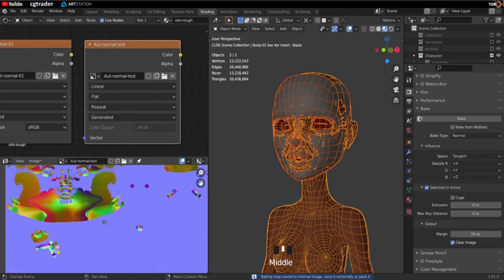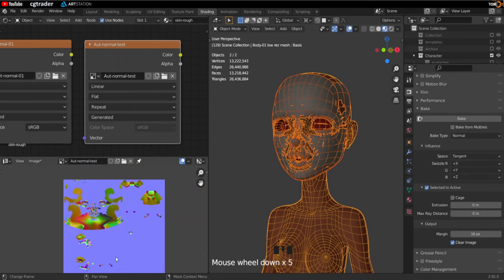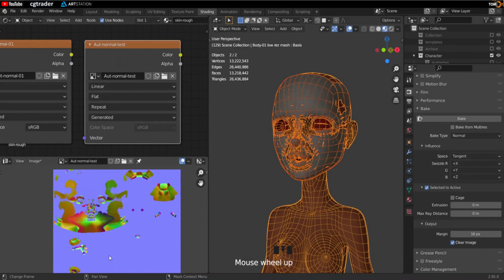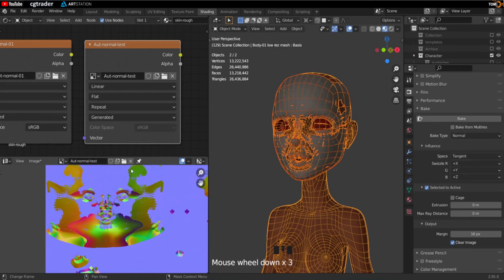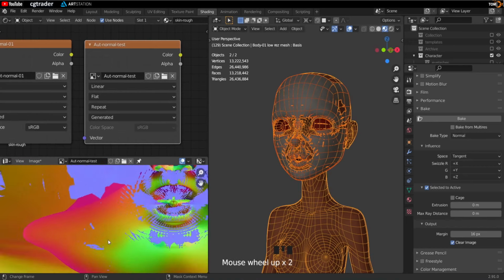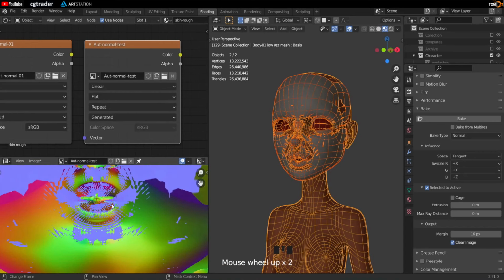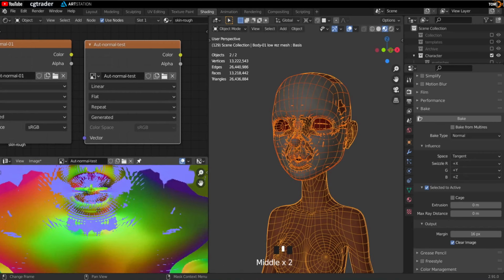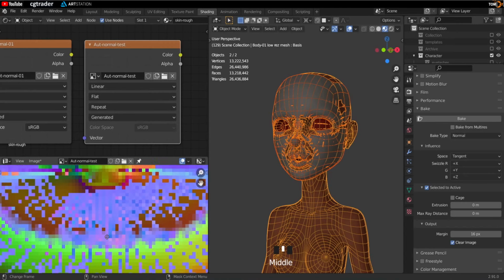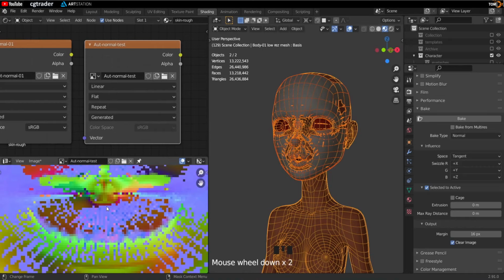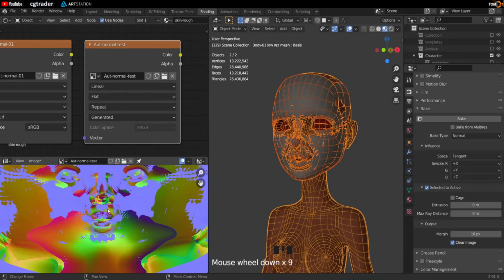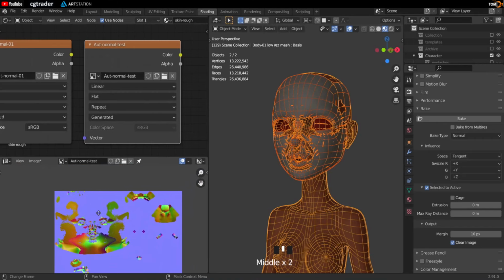Okay, so let's take a look here. For your normal map, everything wants to be kind of purpley. All this yellow and green and bright fuchsia and dark purple, that's all bad. We don't want that. If you look closely, this is part of the lip here. You see how it's pinks and purples, light purples and light blues? That's all good. So we want the whole thing to be as much as possible like that. So this is clearly not okay.